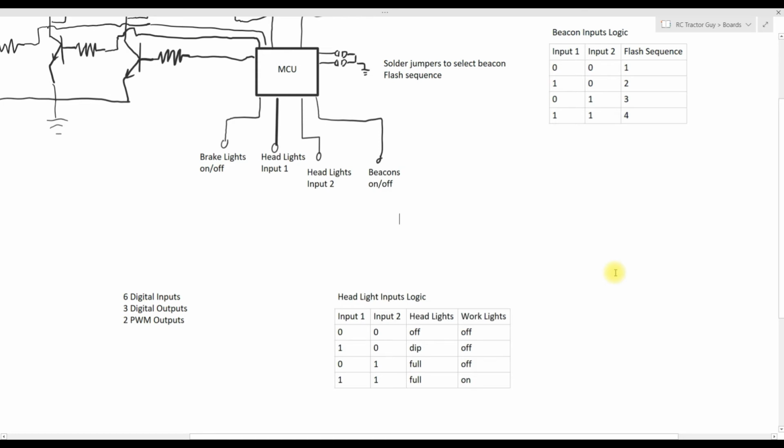Now we want to choose the microcontroller that we're going to use, and since we know that we need 11 inputs and outputs, it might be a good idea to try a 14-pin microcontroller. That would usually be a positive voltage pin, a ground pin, and then 12 inputs and outputs. So kind of sounds like what we need. And I'm interested in trying the Padauk microcontrollers because I've heard quite a bit about them. They're very cheap. The programmers aren't cheap. The chips themselves are quite cheap.